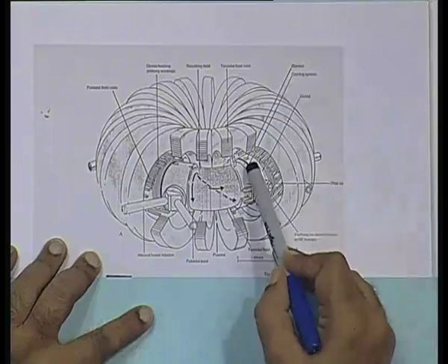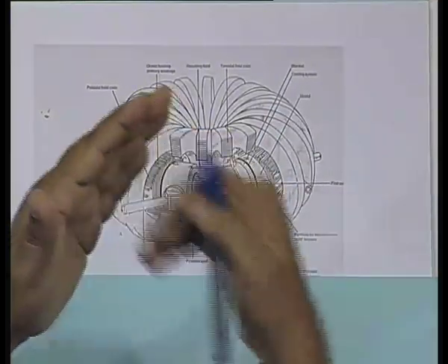So, how does the heat produced get carried away in this system? With the cooling system. Behind the first wall, you have the cooling system, where there are copper tubes. It is behind the first wall, so it is not exposed to the neutron beam. So, you have copper tubes through which water passes. That water heats up, and that is carried to another chamber.